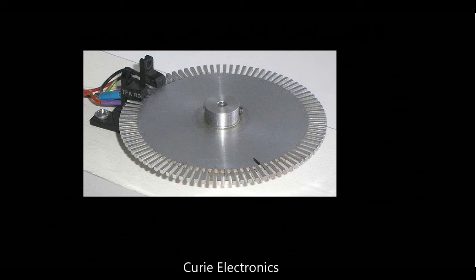Now, see, I have already shown you the video of a simple optical sensor. Here also we are using a similar type of optical sensor. The only difference is that this sensor is mounted in a vertical position, which I have shown you in horizontal position. Now, see, this is a rotary wheel. In the rotary wheel, this is the shaft. This will connect to the motor. This part will go to the motor. And when it rotates, we will get a number of pulses.